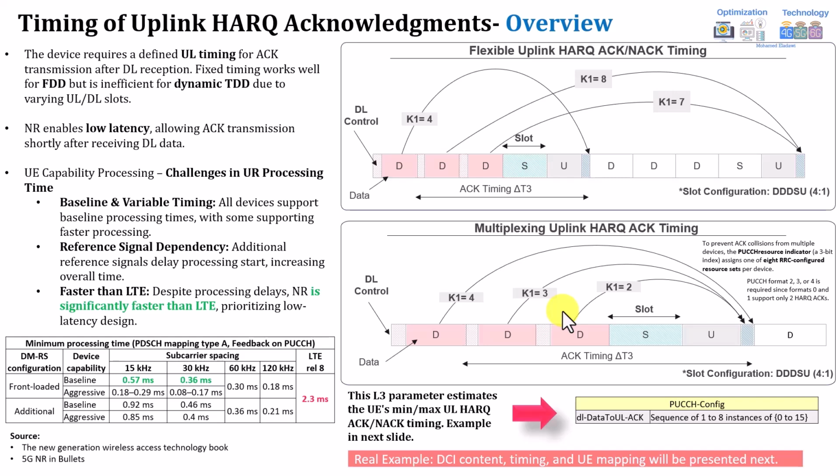And if you have drive test logs, layer 3 messages, and also this information being seen, you can correlate and know when the user will be receiving and when the user will be sending the acknowledgement for the downlink data and the uplink. Let's see the next slide, which is very, very interesting.